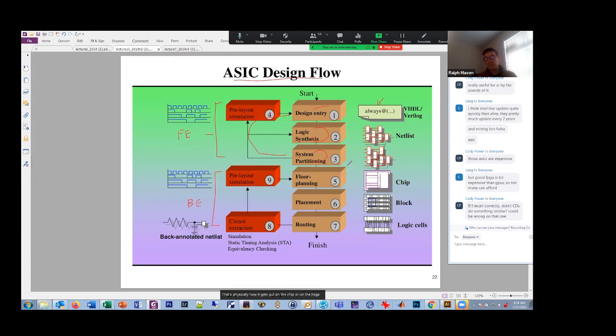In the lab, in FPGAs, this is almost all done automatically. You can go in and modify this if you want, but the majority of the time, we just let the tool do this place and route. When you were generating your bit file, you'll see it go through doing the placement, doing the routing. It's deciding which logic elements things go in, how to wire up the blocks together, and so on. In ASICs, not so simple.